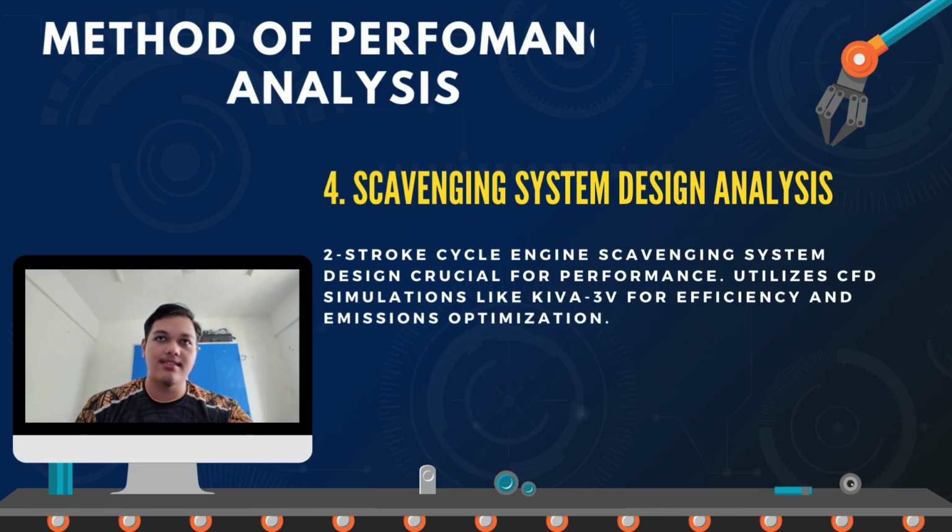The next one is scavenging system design analysis. So what is scavenging system design analysis? The two-stroke cycle engine scavenging system design is crucial for performance. It utilizes CFD simulation like KIVA-3V for efficiency and emission optimization.